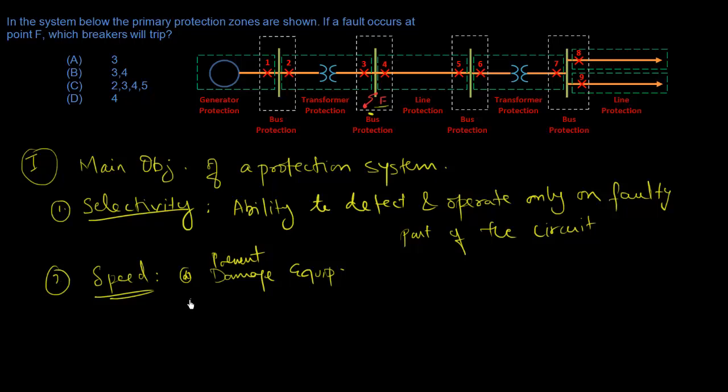B, you prevent undervoltages due to fault conditions, and you prevent another fault from developing. So if there's an existing line to ground fault, you want to clear that fault before another line goes to ground and you have a double line to ground fault.